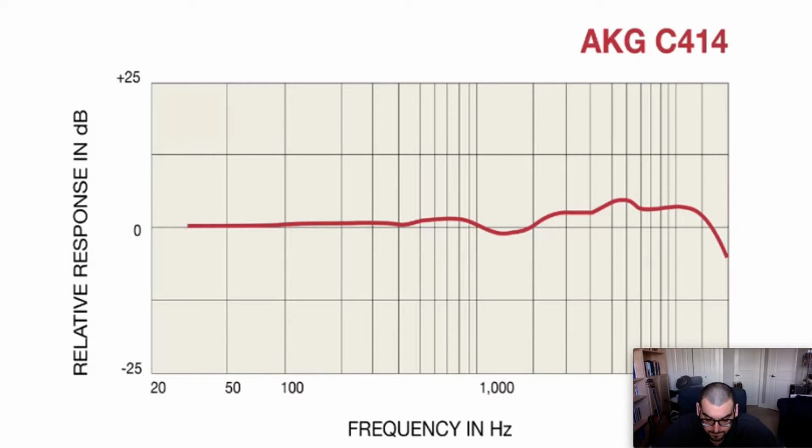Now, these charts are going to differ for different types of microphones that you use. And you might find a microphone designed for specific instruments, like one that goes on a saxophone or one that goes on an acoustic guitar. But the main thing is that you choose a microphone that's designed specifically for your application, whether it be a dynamic or condenser mic. And choosing the one with the right frequency response is an important aspect for that too. What type of sounds do you want it to pick up?